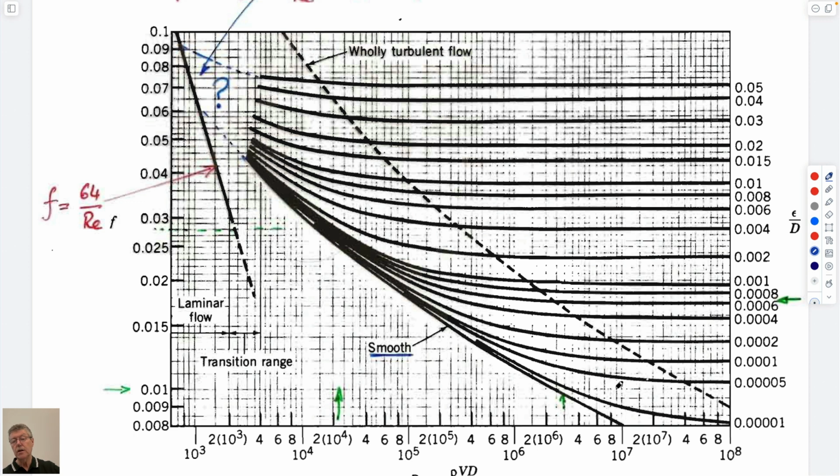And as we get larger and larger flows, we get drag, which is defined in terms of this drag factor, which we can characterize. It's a function only of the relative roughness. So these individual curves are a function of relative roughness, epsilon over d. This curve is completely independent of relative roughness. And so the art of figuring out what pipe flows are is figuring out how to use this chart to calculate the pressure drop between upstream and downstream.